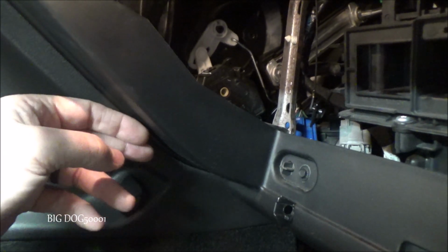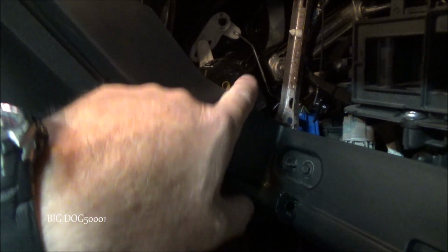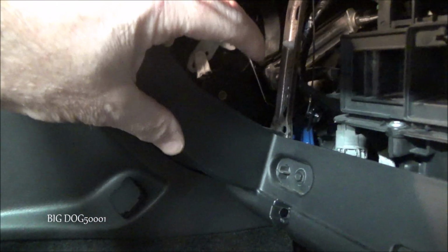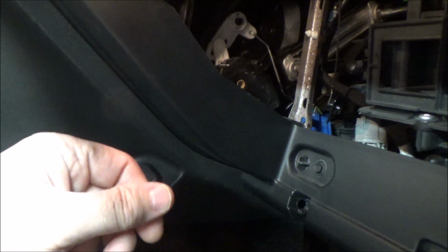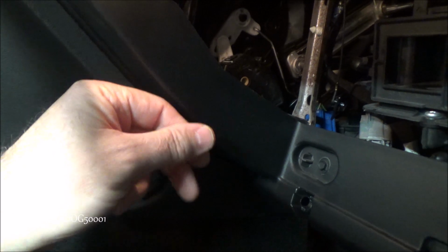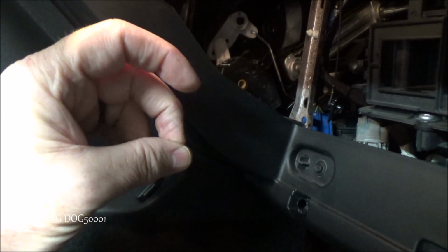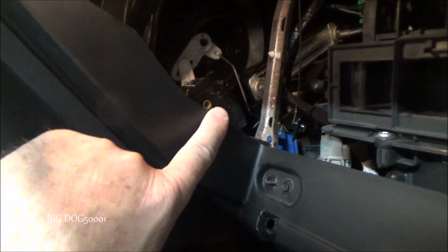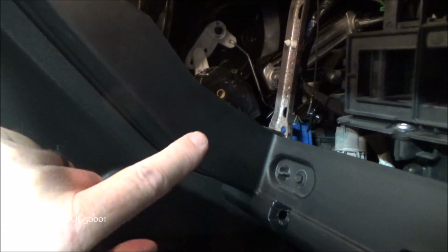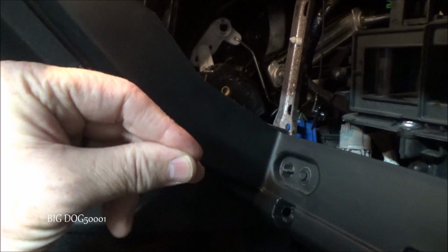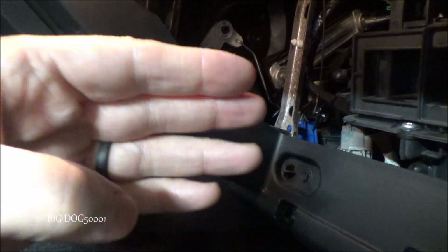Do I have a wiring control problem, or is it more likely a problem with the motor here? And so that kind of verified that my problem is probably up here. And the moment that I plugged it back in, as soon as the little metal contacts made contact with each other, the motor moved and it went right to the position it was commanded to. So our problem on this vehicle was the contacts at the connection to our motor were not very good, and just unplugging it, plugging it back in fixed our problem.